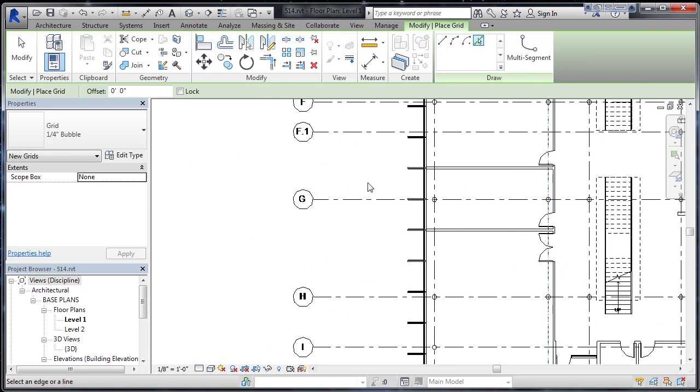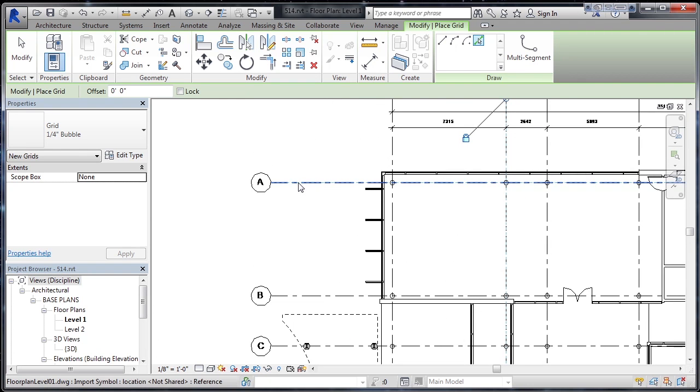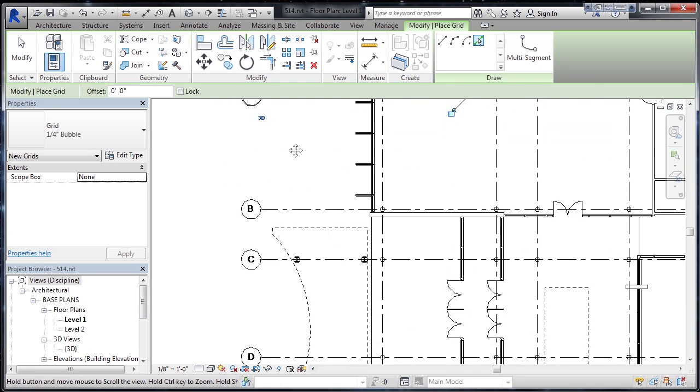Now let's do the vertical letters. I'm just going to go up to A. Click on the line to the right of A. Now, sequentially, it counts 1-2 since the last thing I entered was 1-1. Well, I don't want that. So simply click on the number 1-2 and type the letter A and then hit enter. So that is updated. Now the counter will start with alphabetic characters.